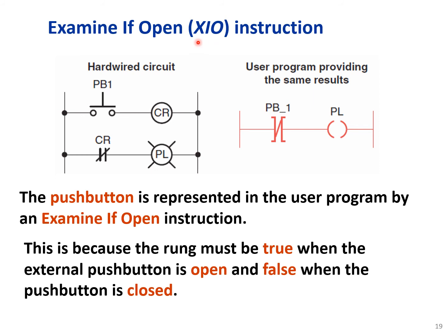Examine if open, XIO instruction. The push button is represented in the user program by an examine if open instruction. So this is examine if open, or negated contact.